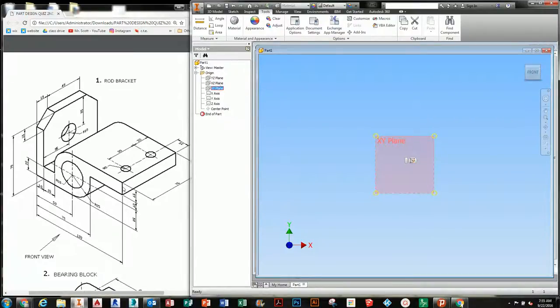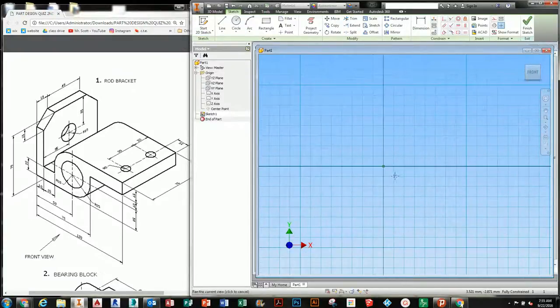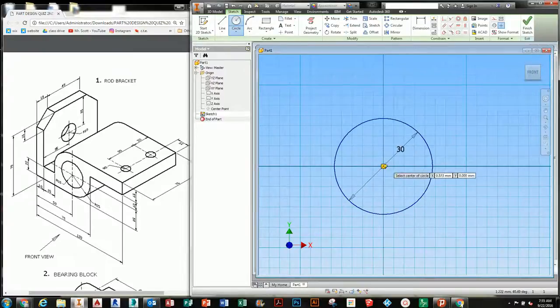And when I create this object, I'm just going to look at the simplest, fewest amount of steps to create this. So I'm going to make this side profile here. I'm going to extrude it out, and then I'll create the holes on the surfaces and chamfer the edges. So I'm just going to start with the circular feature and work my way out. Keep in mind your units. So we've got radius is 15, diameter is 30.